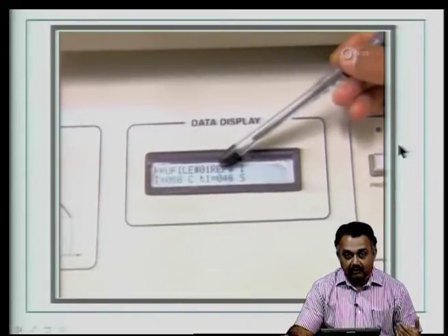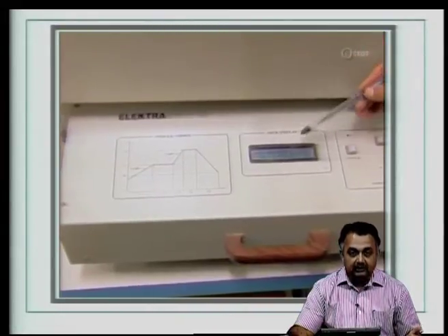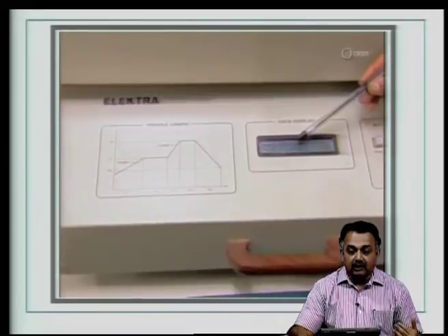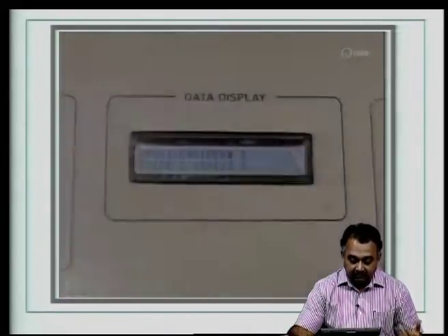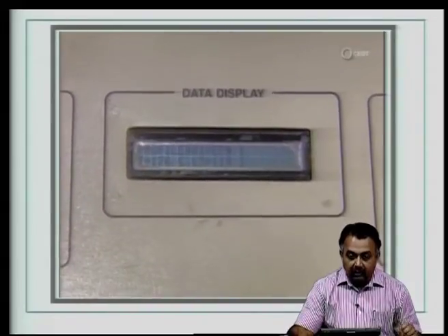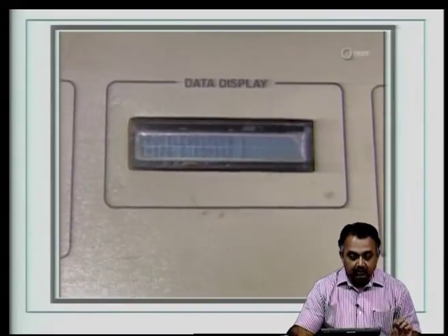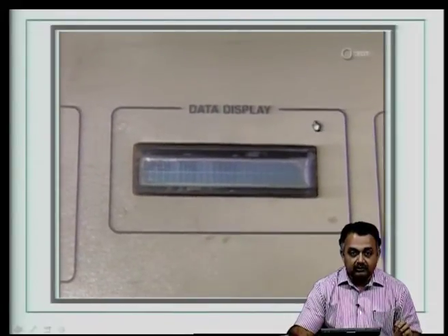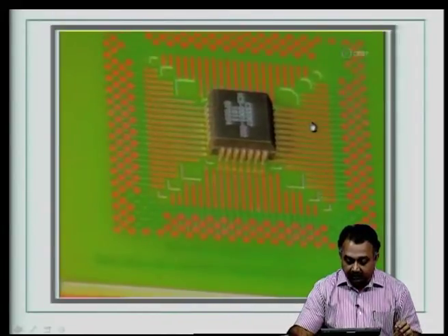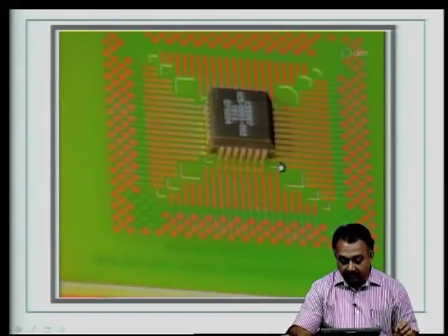So, please do not ignore the thermal profile setting for surface mount device and for reflow soldering process. In wave soldering, it is a different situation. So, note down peak temperatures, note down ramp up timing and temperatures, also note down the soak zones, which are very important, and you can see here a very good attachment.